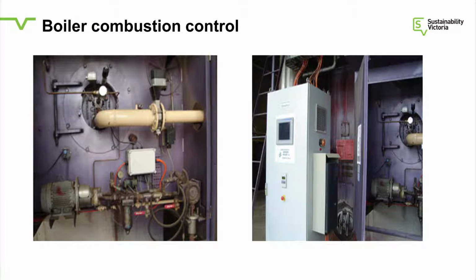So basically the slide there on the left is just a typical gas burner showing the gas train at the top. That one actually has a dual fuel system. At the bottom that's an oil system, so that if gas fails, the boiler could run on oil in an emergency. But basically it controls that valve, it controls the air in perfect ratio, measuring oxygen levels.